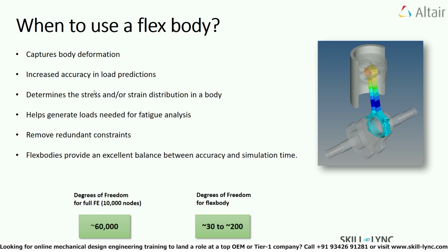This is one of the basic requirements in the CAE world. It is not just sufficient if we compute the forces, torques, accelerations, and displacements at various locations, but it's very crucial that our model has the capability to deliver the stress or strain results depending on the user's request. This is possible only if we build our model using flexible bodies.